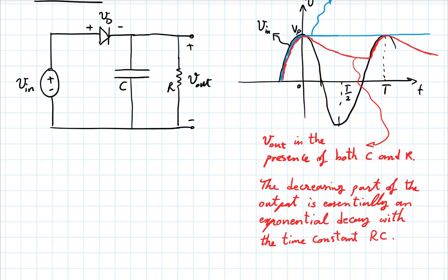So now, we started literally from this point, but this circuit will never come back down to that point again. It will just go up and down between that VP and this lower value here. So you might say the variations between the top and bottom of the signal have become less. It doesn't go all the way to 0 anymore. Now imagine you wanted to build a decent power supply where the variations are very, very little.